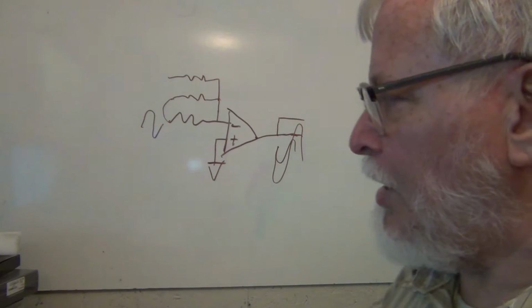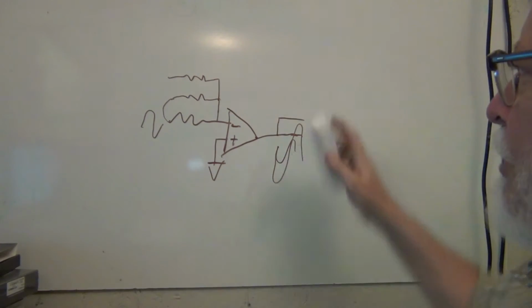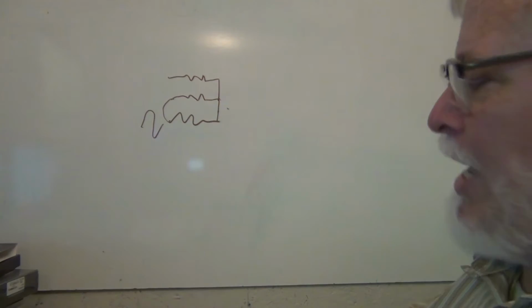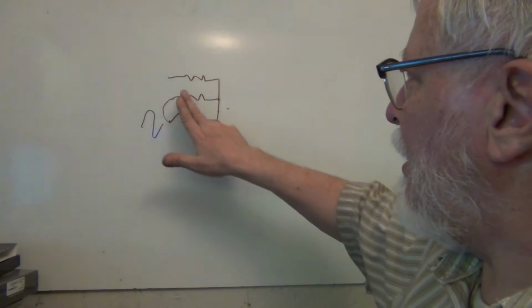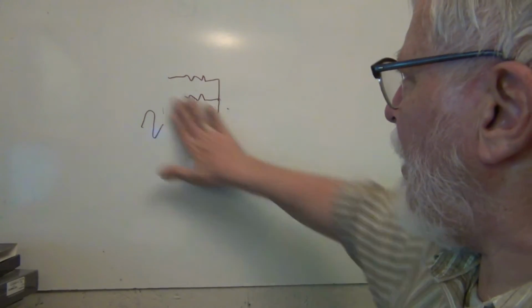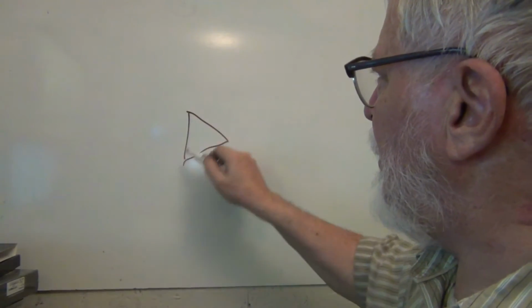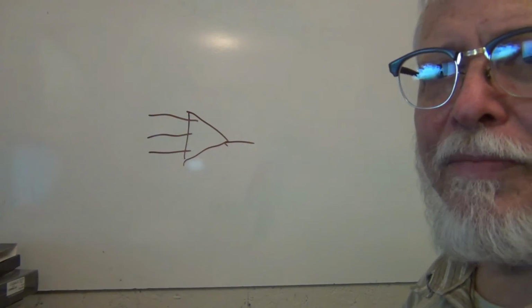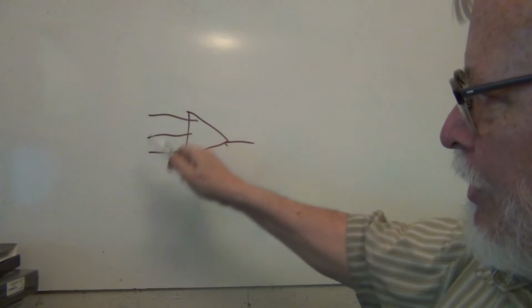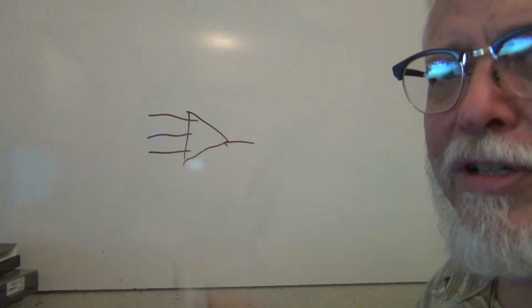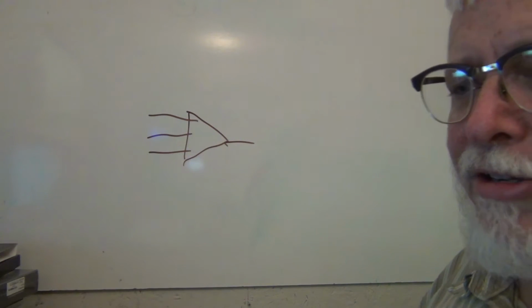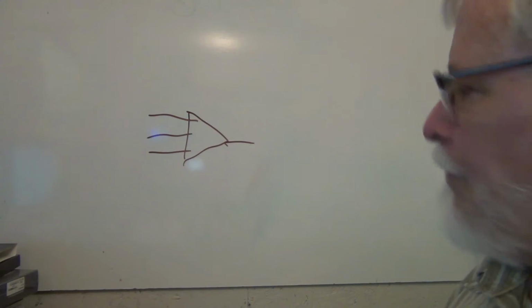Okay, so that's basically what in Scanimate terminology is called a summing amplifier, and the animators always drew a summing amp much simpler than that. They just drew a triangle with 3 inputs and 1 output. So if you need a gain of 3, you hook something to all 3 inputs. So that keeps it simple. You don't really have to understand a lot of the underlying circuitry. It just works for you.